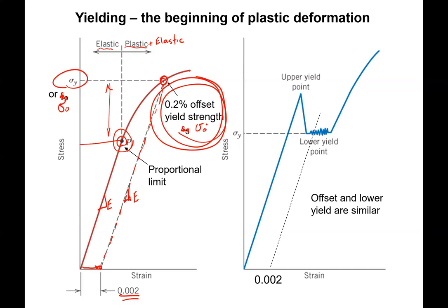Okay. All right. There are some stress strain curves, particularly the plain carbon steels, I should say, mainly just iron and carbon and no additional alloy elements, where the curve may actually continue on up to some particular point. So this is all elastic. And then when the curve deviates from this, the stress actually drops. And then we get what's called serrated yielding. And then the curve would then start continuing on and behaving like the rest of most samples. We'll take a look at that apart in a minute.